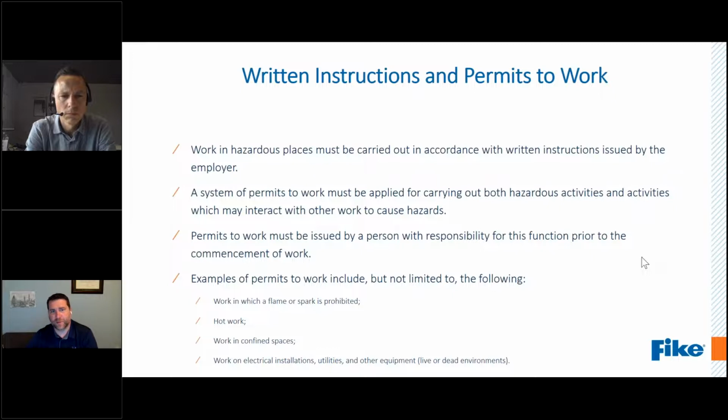But this also talks about written instructions. It goes back to that talk about operating procedures: you should have written operating procedures for your operation that cover startup, shutdown, normal operation, but also abnormal conditions and emergency shutdown. So you need to have those procedures in place and then review them with the operators. That's part of their job, that they have these procedures, they're trained on them, and they know how to operate safely.